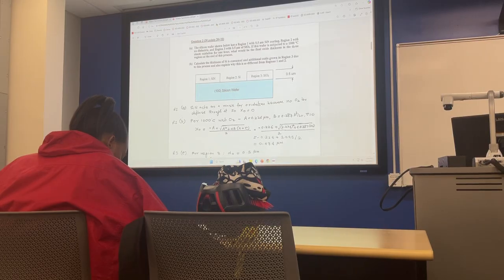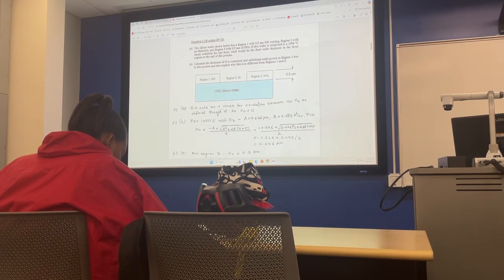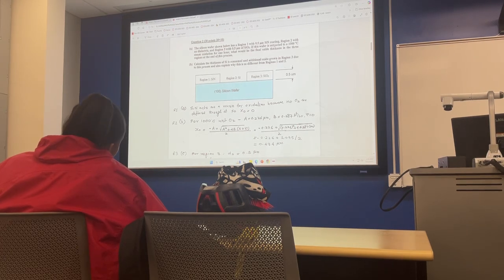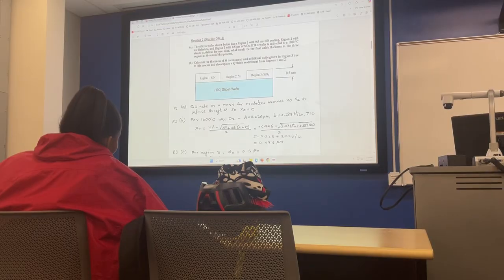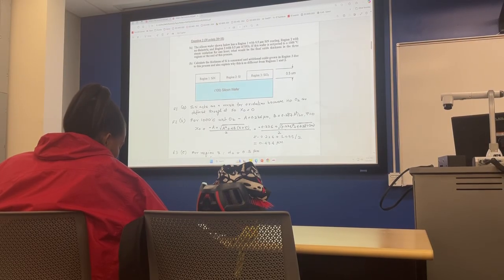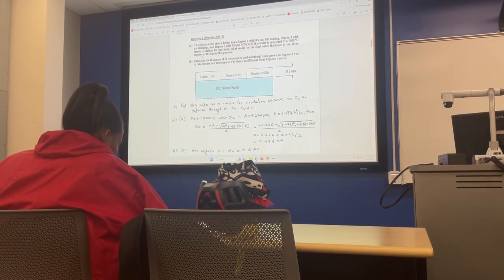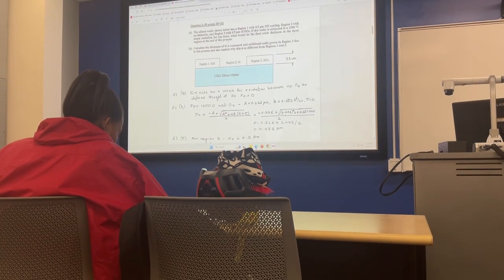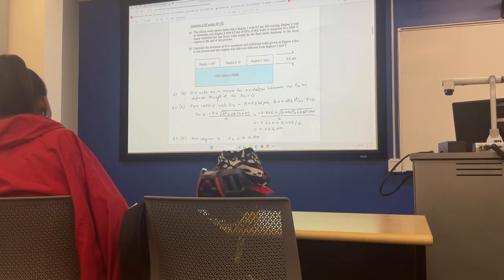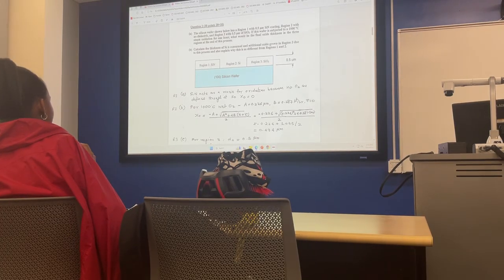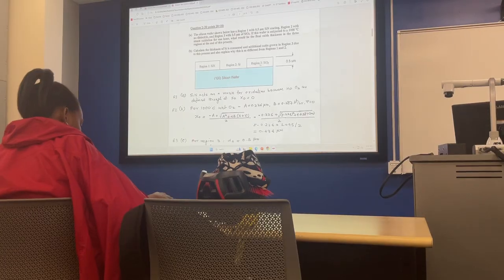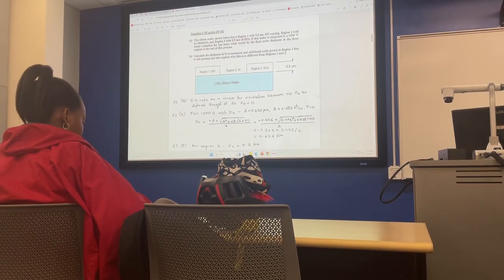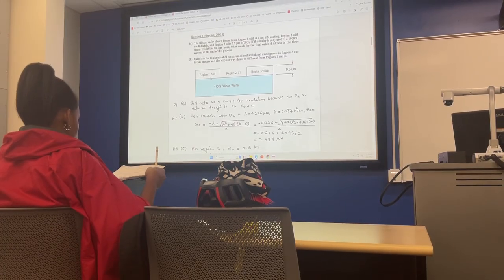Problem 2 I thought was very straightforward, and a lot of you got this all right. I just gave a little picture, and I said I'm doing an oxidation here, and gave you one condition for oxidation: the whole wafer is put inside a furnace at 1000 degrees with steam oxidation for 1 hour. Tell me what would be the final thickness of the oxide in these 3 regions, right? Some of you just somehow remembered that there is no oxidation through nitride.